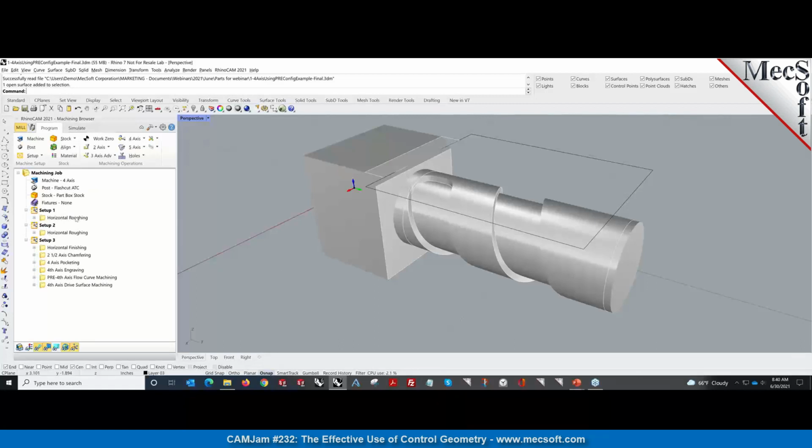One other note that I should make is about 5-axis. When we talk about 5-axis machining, you're always going to be using that in combination with 3-axis methods, because there's a lot of power in locking the tool axis and machining with the locked tool axis. And there's a lot of toolpath methods we have in 3-axis that you can leverage. And so seldom will you machine everything using 5-axis. So there's always a combination.